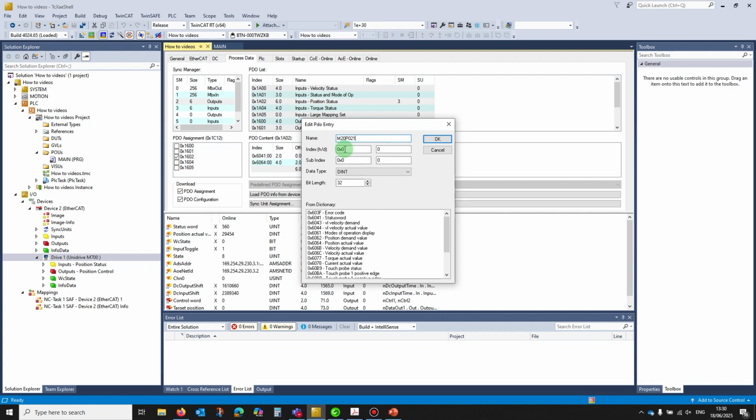There we go. So I'm going to fill in the hex value, which is 20, and then menu 20 is this last part converted to hex, which comes out as 14. And then I'm just going to enter the parameter number here. So in this case, it's 21. The data type is pre-selected. It must have been the last thing that I did. So that's set as dint 32-bit.